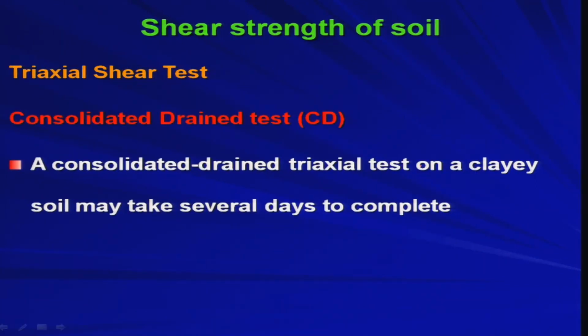A consolidated drained triaxial test on a clayey soil may take several days to complete, agreed, because as you have seen from our consolidation chapter, consolidation itself is a long process, it is a time dependent process, right.